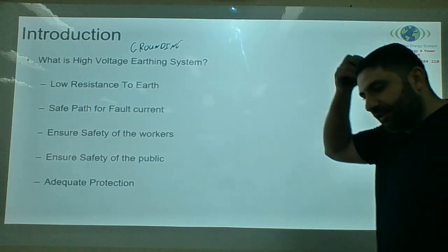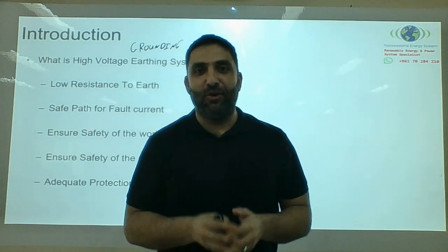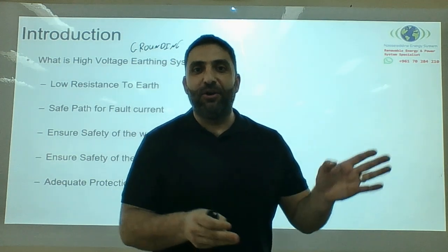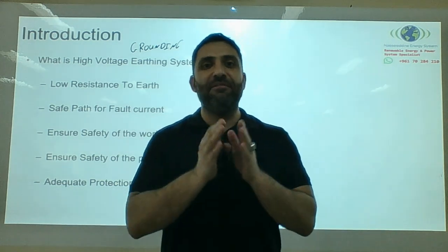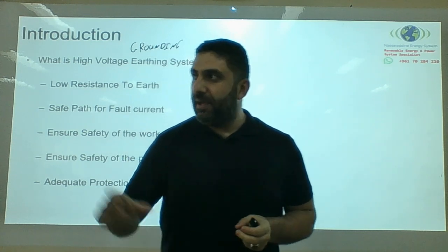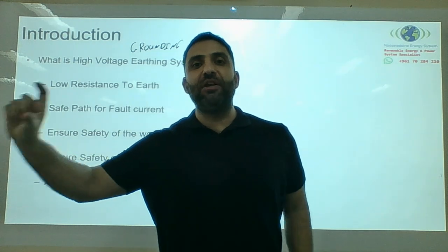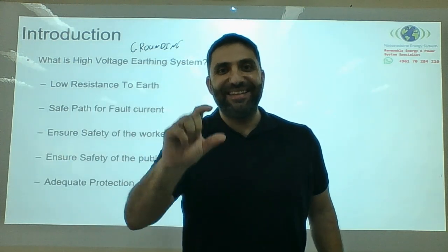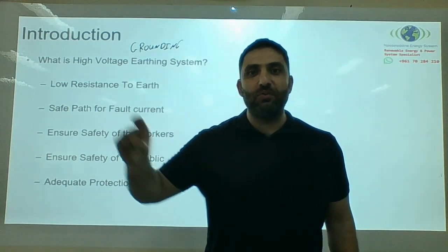Adequate protection. For those who studied protection or work in protection, they know that soil resistivity or the earthing system plays an important role in the setting of the relay. Based on your fault, if you have a fault at the substation, the fault impedance will be the resistance of the substation, and the magnitude of the current will depend on it.